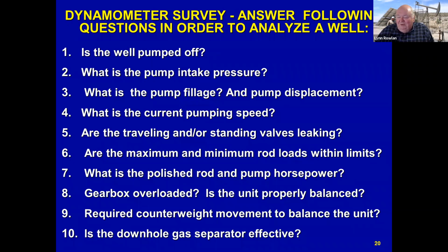Now, an accelerometer is what you have in your vehicle or your cell phone, and it measures the change in velocity. So we measure the change in velocity with the accelerometer, and that gives us a position versus the time of the stroke. And the load versus time, we plot the load versus position. We call it a dynamometer card. So we can determine, based on the surface dynamometer card and what's down at the pump, is the pump full or is it partly full?